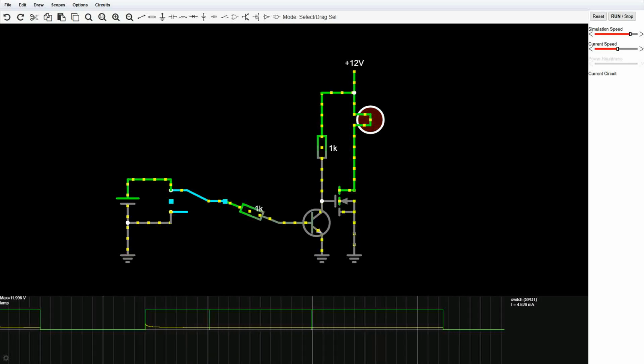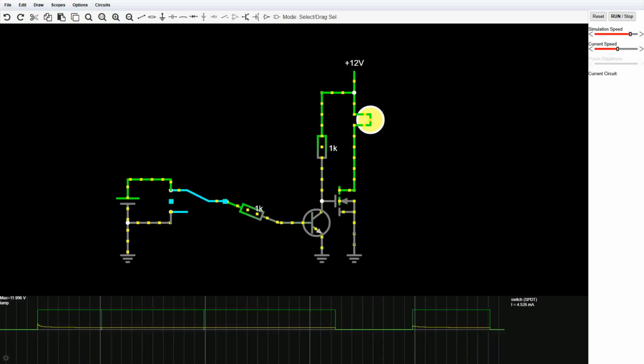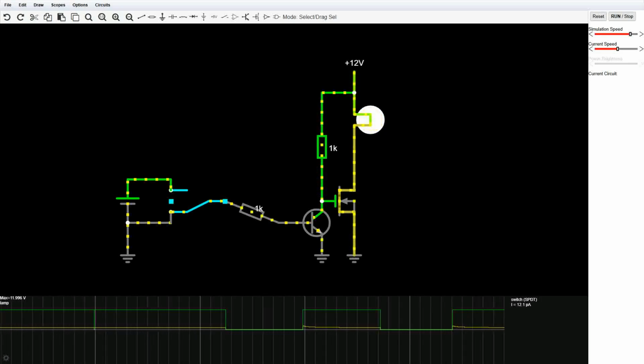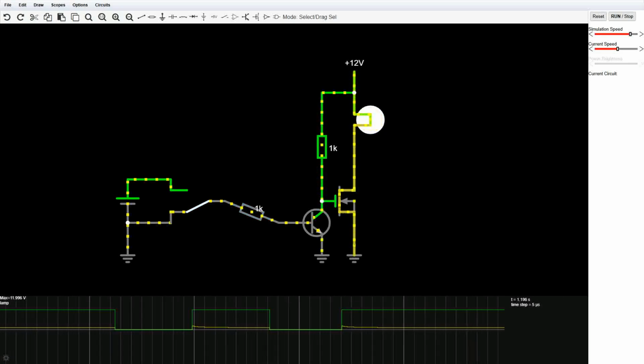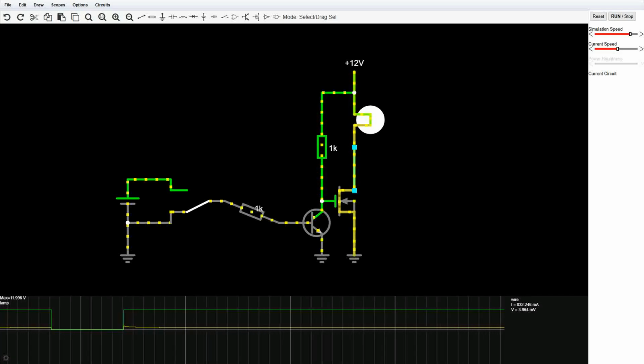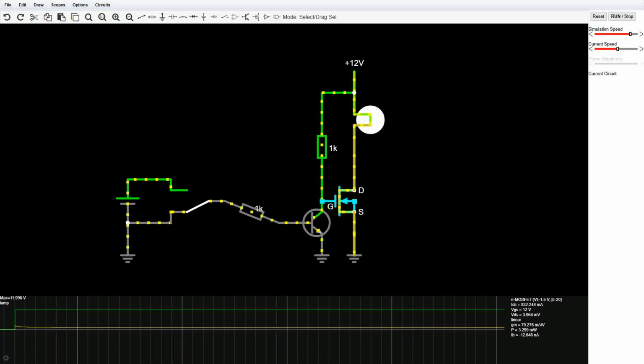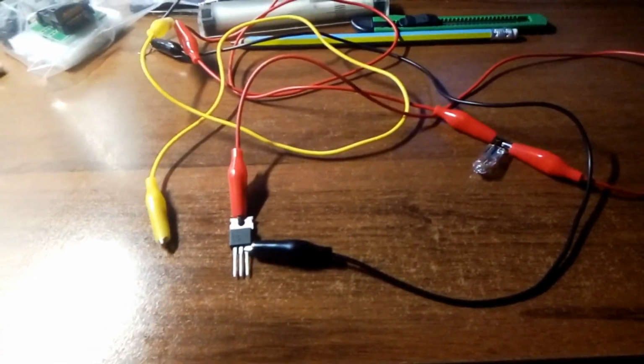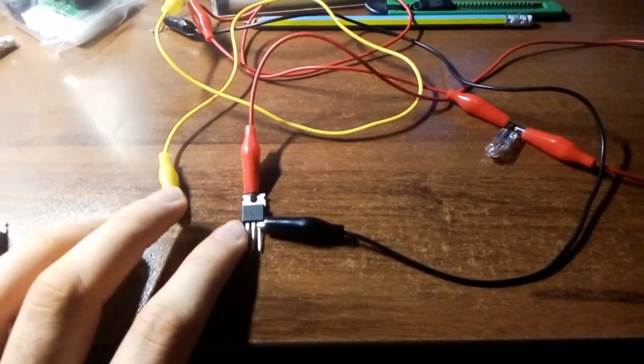But be aware that it reverses the polarity of the control signal. Now the high level input turns the MOSFET off, and low level turns it on. To switch your MOSFET off, you must discharge the gate. Otherwise, it may stay on even with zero input.